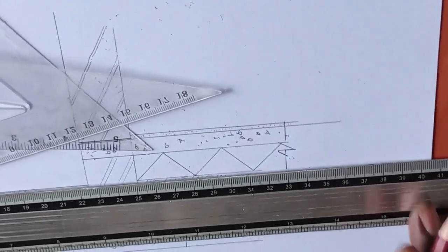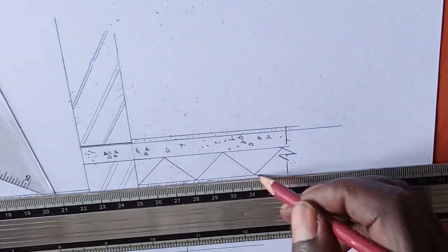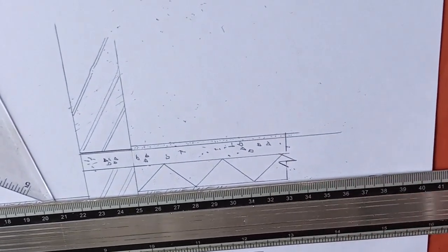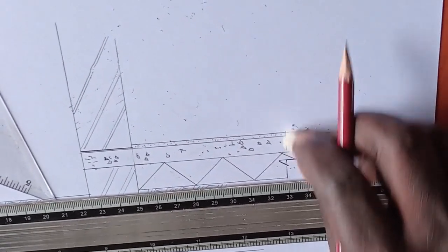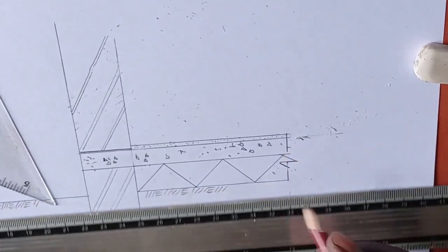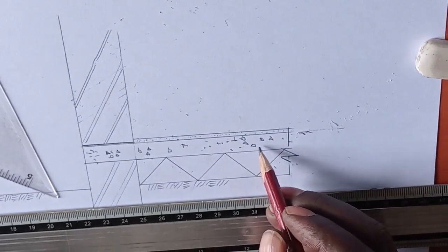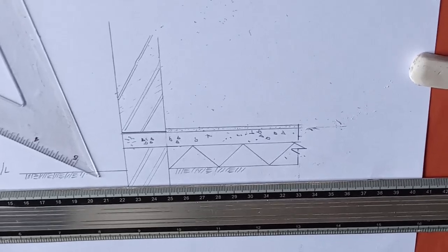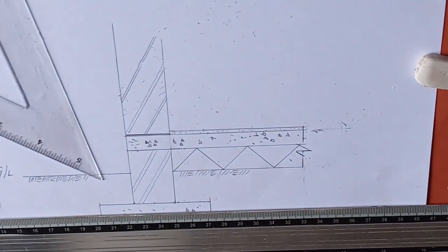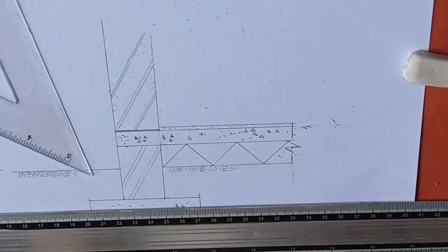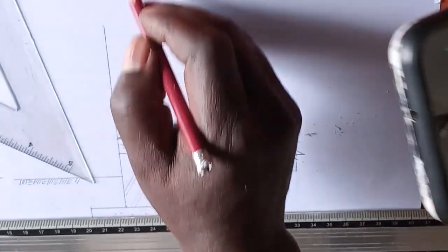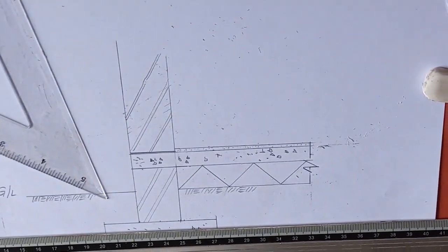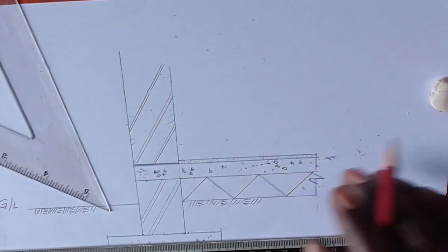So I can connect this line. I've shown you in first term how a broken line looks like. So this one we can clean it off. This broken line shows that our hardcore is continuing, our side concrete is continuing, even the screed is continuing. Other than that, we have stopped it. Our paper cannot now accommodate. So that's what we call a broken line. Here also it means this external wall is going upward. The only thing we are going to show to stop it with is using a broken line.